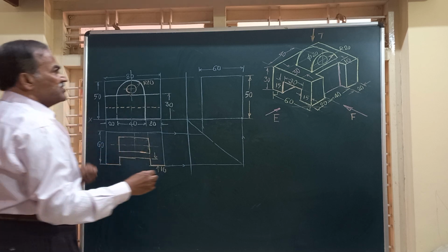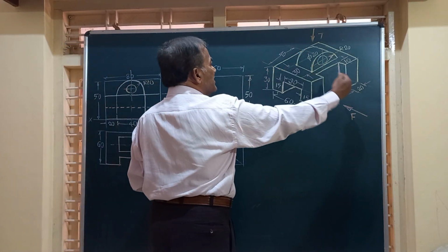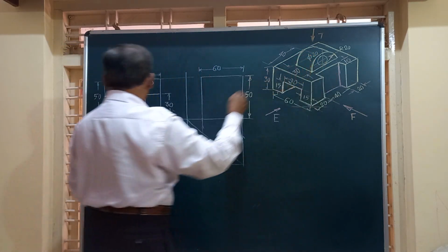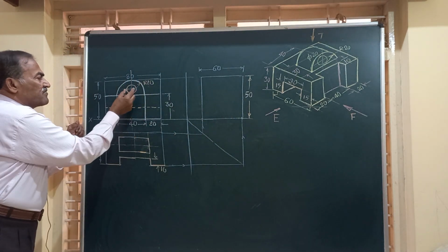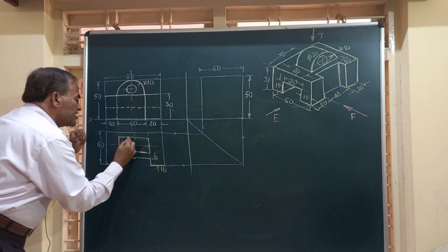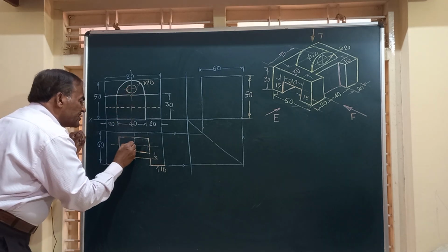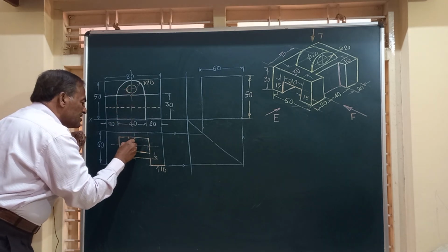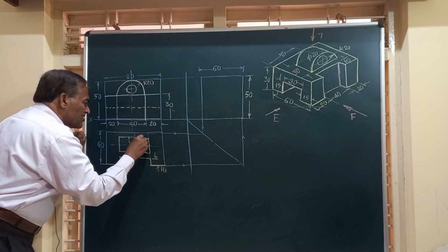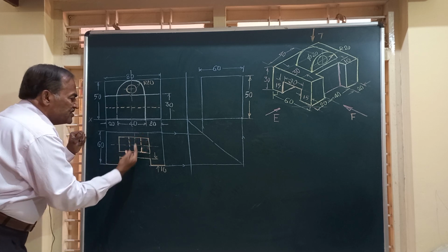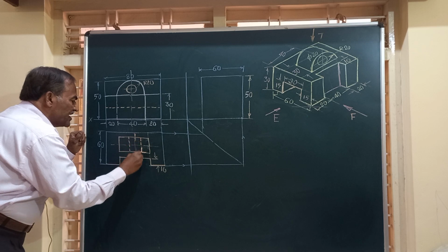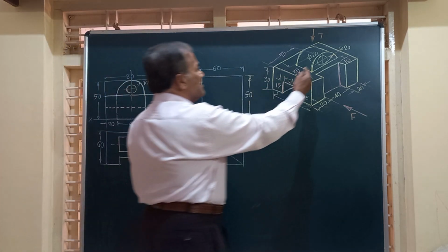This is the rectangle you see here, and there is a hole drilled in that. That hole can be obtained by projecting from these, and there is going to be a hole cut here. So I can project from here, or I can take the same distance on either side of this slot and obtain it. Friends, this represents, with the axis, the slot that is drilled here.